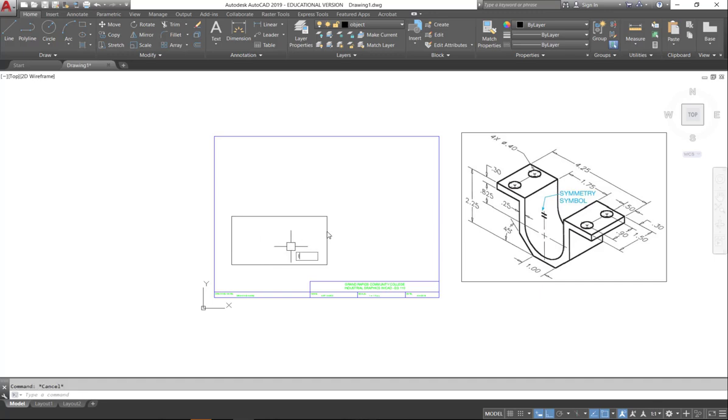I'm going to put my miter line in now. And I'm going to bring that up there. I'm going to tab over 45 degrees. There that is. I'm going to copy this line, and this line, because I know that represents the top. The right side. I'm sorry, the front. This line represents the front, the top and the right side.